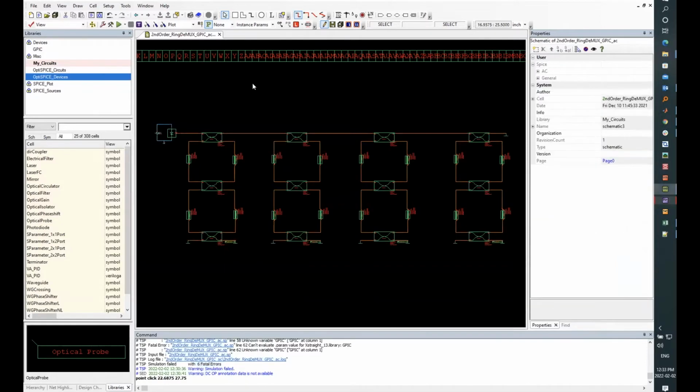from the SEdit, whenever you hit run, it extracts a netlist and then it runs from the netlist. Now, for some reason, there is a bug in the Tanner platform at the moment, and we are working to correct this bug. So when it extracts the elements in the netlist, for some reason it is missing a semicolon definition. I'll show you what I mean.